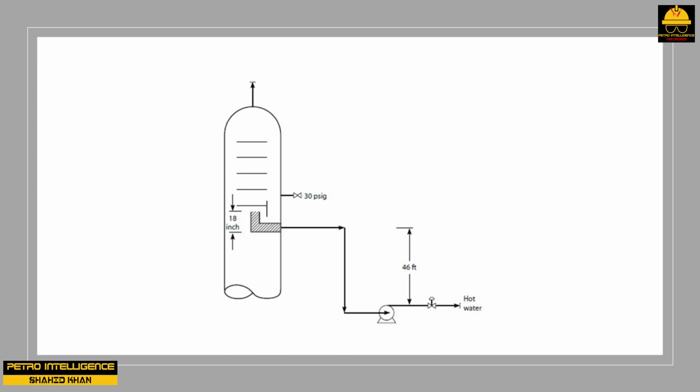But this is still a lot more available NPSH than the 14 feet of required NPSH needed to pump 110 GPM. If I now open the discharge flow control valve sufficient to increase the flow from 100 to 110 GPM, or by 10%, this will increase the frictional loss in the suction piping by about 21%, or about 0.5 psi. Delta P varies with square flow. But this is not what I observe. The suction pressure in the picture slips from 47 to 36 psig, at which point the pump begins to cavitate. What is happening?